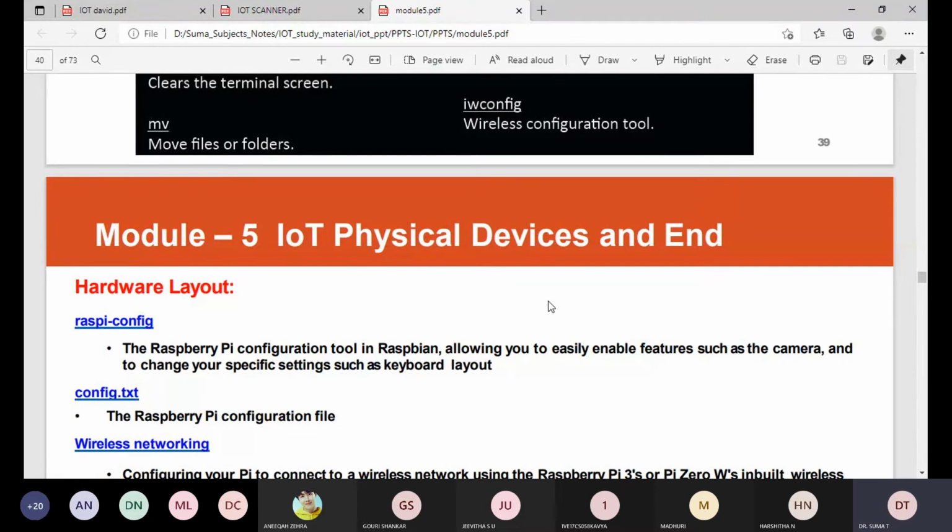That software is going to give you instructions for what to do, what not to do, why and all. Okay, and follow the instructions to install the software. Whatever instructions it gives are the guidelines, right? So we have to follow those instructions. Then insert the SD card into the computer or laptop SD card reader and make a note of the drive letter allocated to it. In SD Formatter, select the drive letter of the SD card and format it.